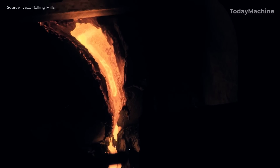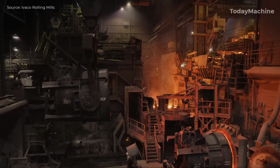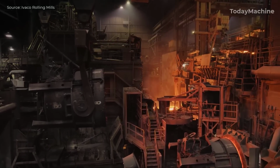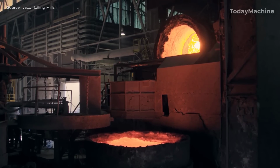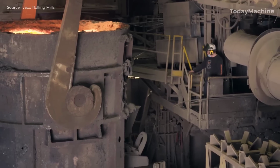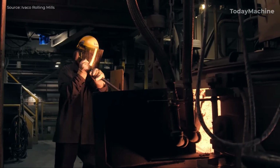The scrap is charged into the furnace through a continuous charging system, and the melting process begins. During this stage, carbon and various alloys are added to achieve the desired chemical composition of the steel. Oxygen is also injected into the furnace to enhance the melting process and achieve the necessary temperature.